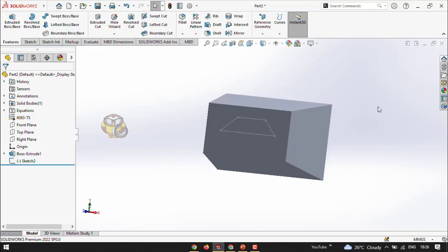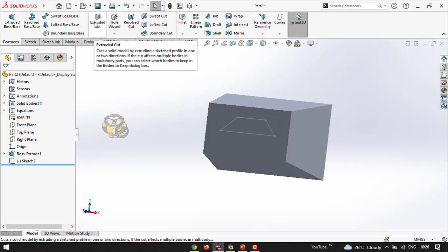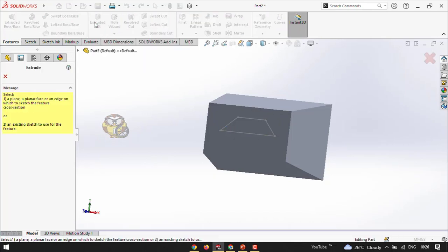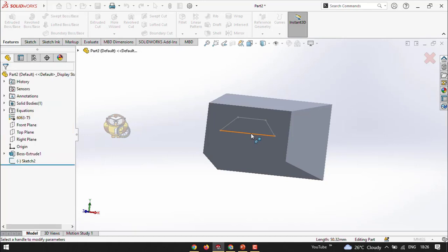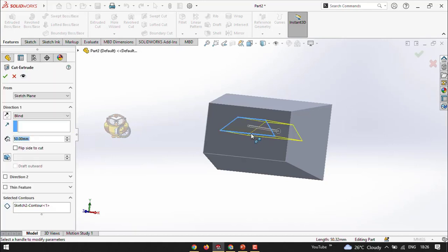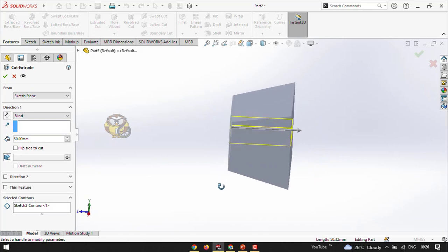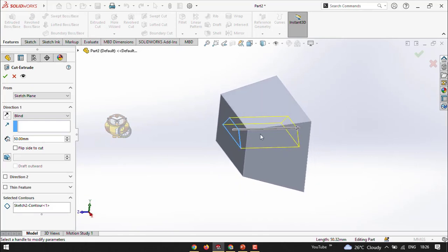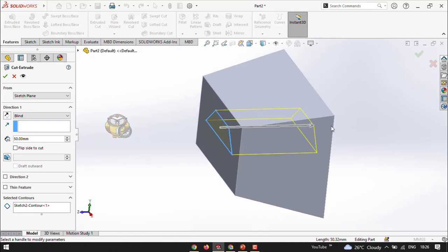After updating my sketch, now I am going to extruded cut. Now I just go to select the extruded cut. So same, this yellow color message, they are asking us to select the sketch. Just I go to select the sketch. Once I select the sketch, see, automatically this takes the direction. This direction will remove the metal. So automatically it's taken. You can change the depth.